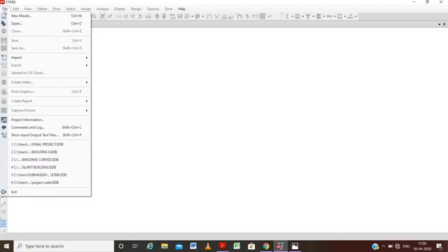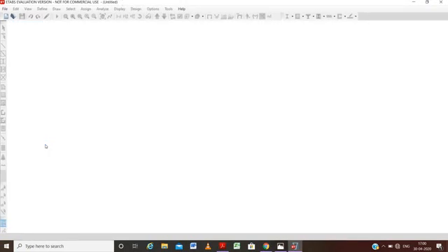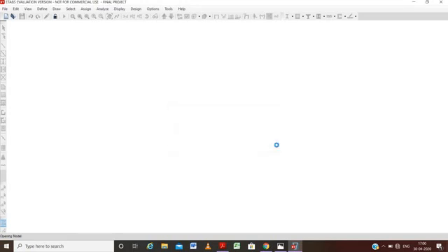In this video, today we will open the same model which we have done earlier, but in this model we will use seismic load. Seismic loads are the loads subjected to a building when an earthquake occurs, meaning these are the loads that occur on a structure at the time of an earthquake. Today we are going to analyze how a seismic load is going to affect a building. We will analyze it by two processes: one is the response spectrum process and another is the time history process.